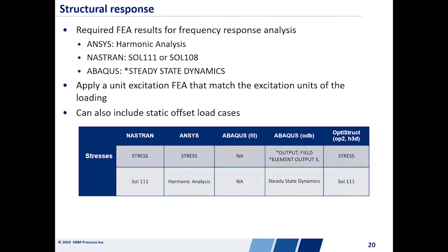Now, the input into the fatigue roadmap for structural response is going to be your FE results. As I said earlier, in most cases we're going to be looking at a frequency response analysis, so we're going to have real and imaginary components. Depending upon the FE tool that you're using, they call that slightly different things. For example, ANSYS uses the terminology harmonic analysis. In Nastran, you would be running something like a solution 111. But in all cases, there are some considerations we need to take into account.